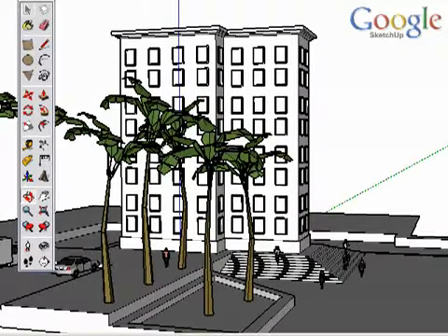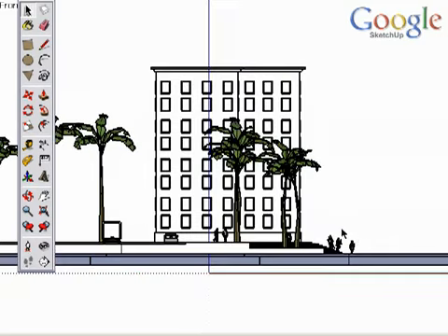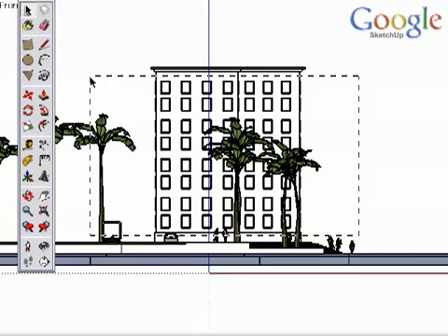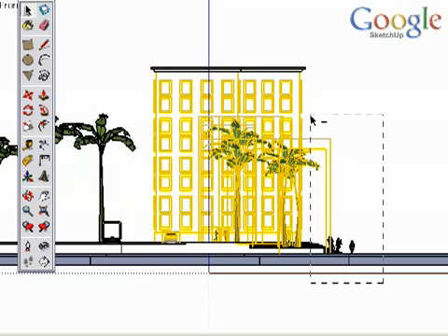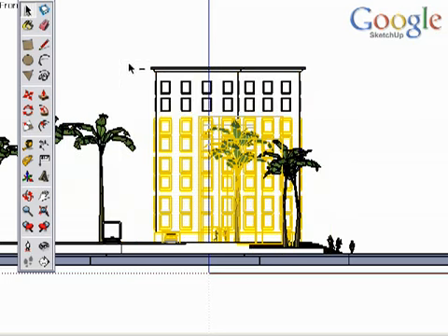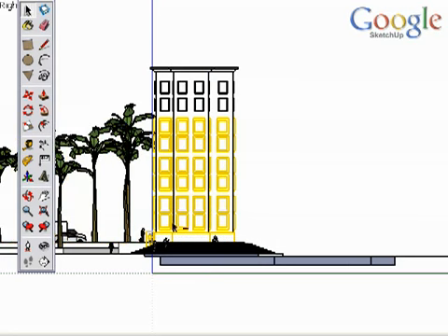We want to select several rows of windows again, but now there is a lot more in the way. Toggle Perspective off, pick a view and make a big sweeping crossing selection to select everything you need. Then use the modifier keys to only subtract from the selection and do several crossing windows to remove objects. You can also toggle other views if needed, but the result is still a good selection that you achieved quickly.